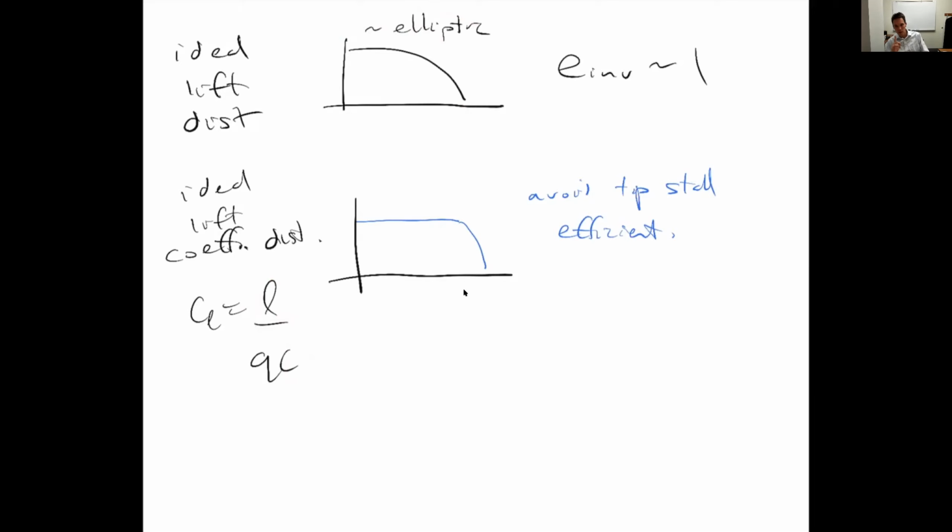One more detail though that you need to keep in mind, and you're going to have to think about this. I'll probably talk about this again in class a couple times, or on Slack when we talk about this. These two conditions do not occur at the same wing or airplane lift coefficient, or another way to say it, they don't occur at the same angle of attack.